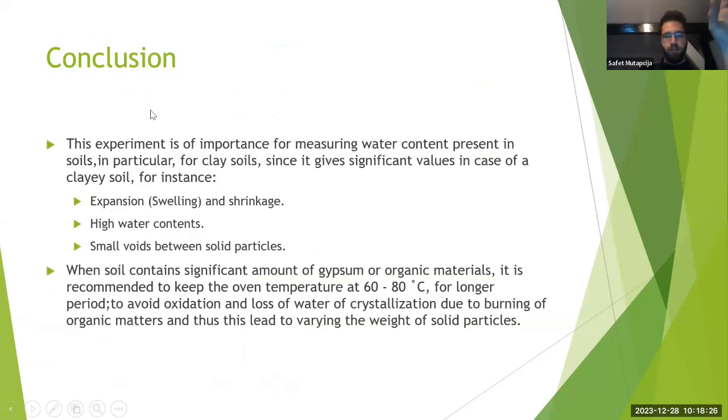So the conclusion for this test is the importance of measuring the water content present in soil, in particular for clay soils, since it gives significant values, for instance, expansion or swelling or shrinkage. With high water content, you're going to expect really high settlements and small voids between solid particles.